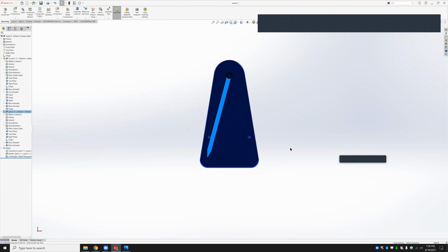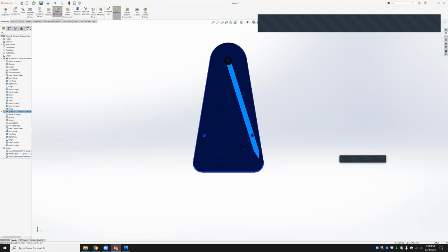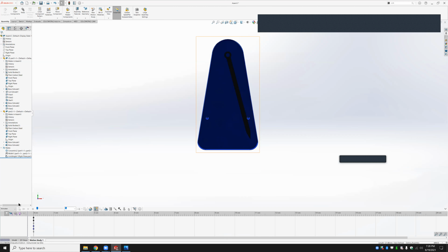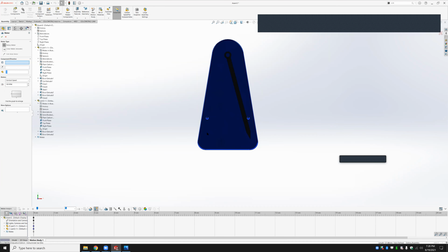This is a buggy mate, and usually it's not this buggy, or it hasn't been in the past for me, but we can see that this is now free to go in between, and sometimes it breaks. I'm pretty sure that's it breaking. And if we have a doubt about that, we can try to use a motion study to see if that is the case.